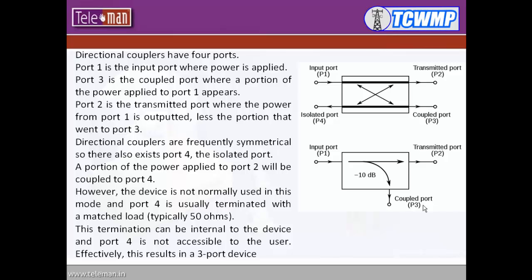In the second diagram, you can observe the input minus the coupled port, that is port number 3, and the output you will receive at port number 2. However, the device is not normally used in this mode, and port 4 is usually terminated with a 50 ohm load.